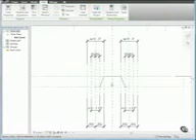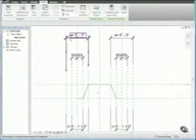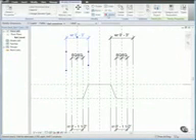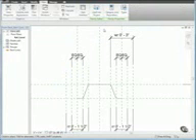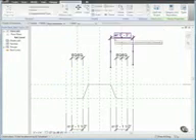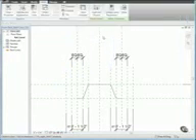Select the parameter WR as shown and click Delete. Then delete the same parameter on the opposite side of the profile. Then delete some additional vertical reference planes and parameters until the view appears as shown.